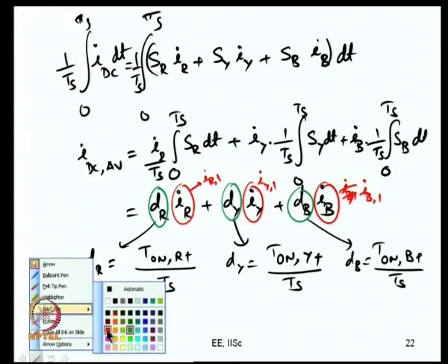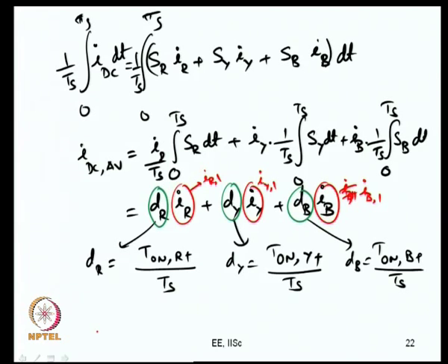So, let us go to sinusoidal PWM now. In case of sinusoidal PWM, what do you have? You have your modulating signal MR equals Vm sin omega t. Is that right? This is what you have, and what is your duty ratio of R phase? This is something we had done in an earlier class. You can now see that this MR would vary from -1 to +1 corresponding to your duty ratio variation from 0 to 1. You can relate to the duty ratio.